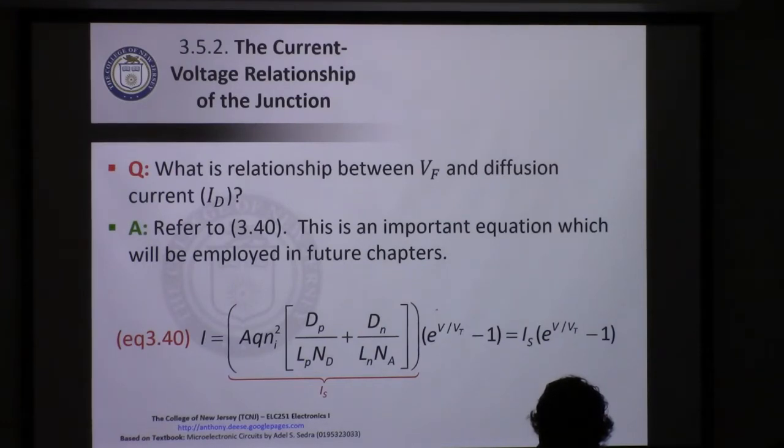So yeah, the thermal voltage we described a while ago when we were talking about the Einstein relationship. Normally it's about 25.8 millivolts. It scales the behavior of the exponential model. Obviously, the value of e to the whatever will be less than e if V is less than VT. It essentially just scales how the thing works. V sub T will be equal to 25.8 or 25.9 millivolts, depending on what the temperature is and what the parameters are set for the example.